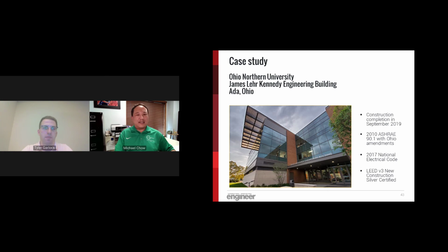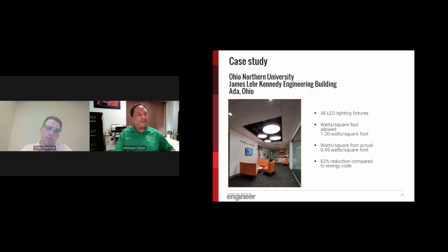Just a quick case study on a project that I worked on and designed. This is a new engineering building in Ohio. Ohio had ASHRAE 90.1 2010 and the 2017 NEC, and it got LEED version 3 certified. This project used all LED lighting fixtures, and the watts per square foot allowed by the COMcheck that we used was 1.2 watts per square foot. We actually came in at 0.45 watts per square foot, and that's a pretty significant reduction compared to the energy code.